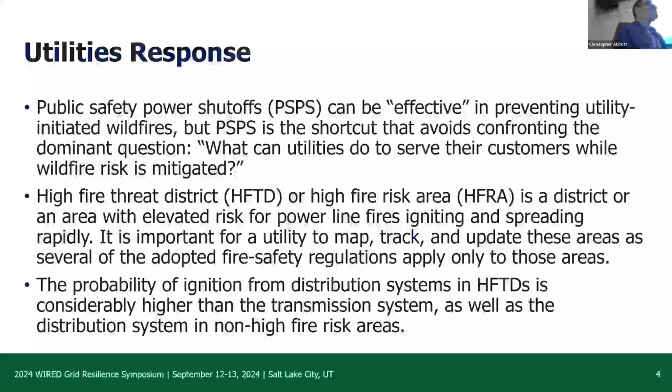One approach is super fast protection devices. In distribution power grids, I think Farnush had a very cool graph, because we have short electric distance. The problem is that detecting traveling waves, which can enable fast tripping protection schemes for detecting the falling conductor or high impedance faults in the system, is super hard in distribution systems. What will be the solution? The cool sensor that Farnush presented. We did a study supported by the Department of Energy in collaboration with Sandia. We found that in order to identify a falling conductor or faults in a distribution system, we need microsecond time steps in the data measurement, which means 1 million data samples should be measured every second.